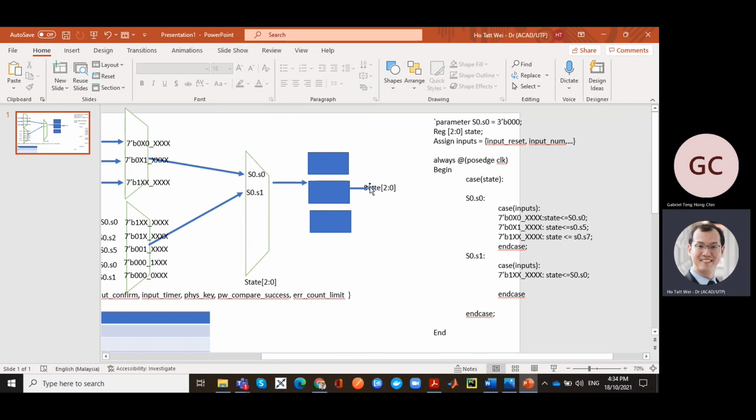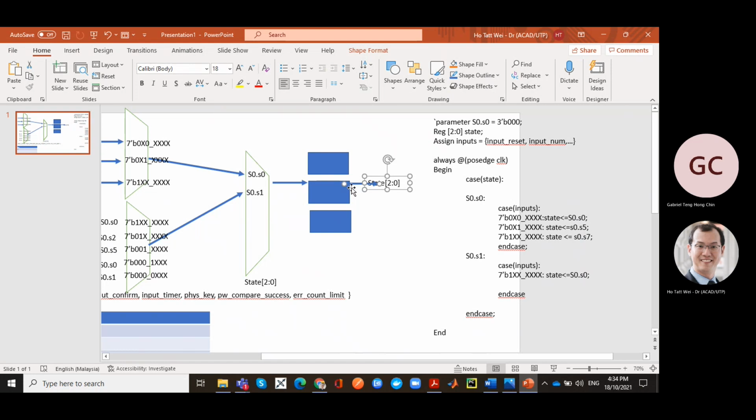Actually, Q plus is just the previous state. Q is just this low. Q plus is this input low, and Q is just this output low. So you're still designing a combinational logic, but now this is considered the input. That's what you're doing when you design the sequential state machine from your digital logic. If you go and look at it, you're still only designing the truth table for the combinational part, not for the sequential part. Okay?